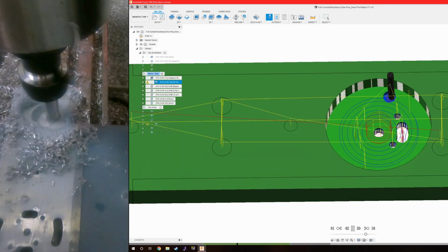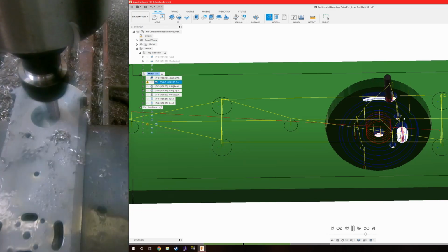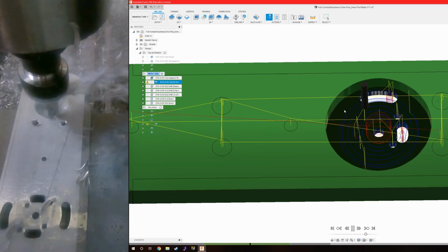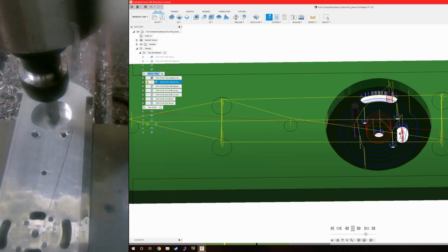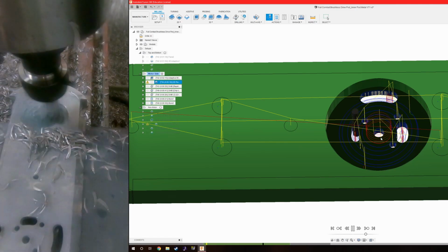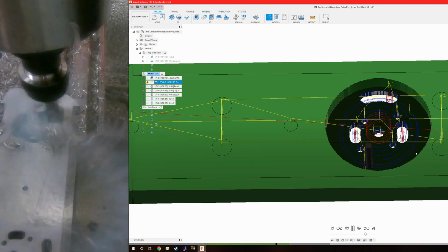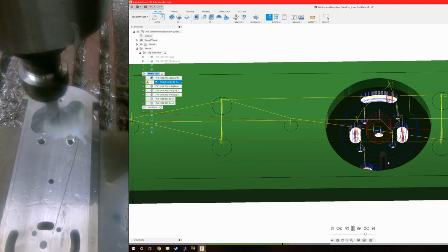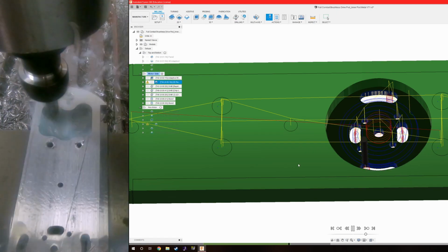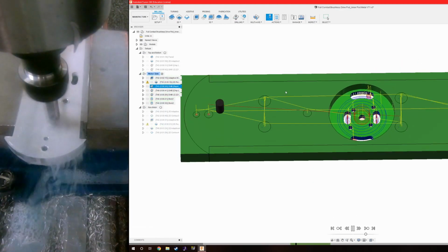Then I'm coming in with this 1/8 inch end mill, and I'm doing all of this pocketing out that I need to do for ventilation for the motor, and also for where the screw holes for the motor will be, so that I can actually mount it in the robot. And also these larger pockets allow the actual wires for the motor to be fed through them.